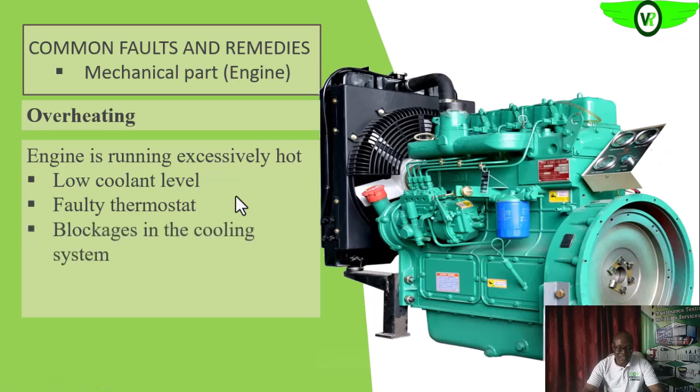Then if we have blockage in any of the parts of the cooling system, because if your cooling water is dirty, that can form a deposit within the engine. We saw earlier when we were looking at the block, those water passages.